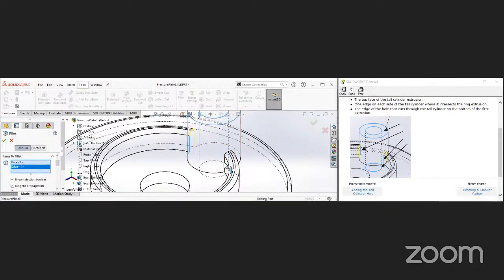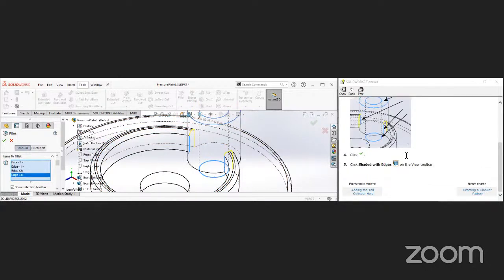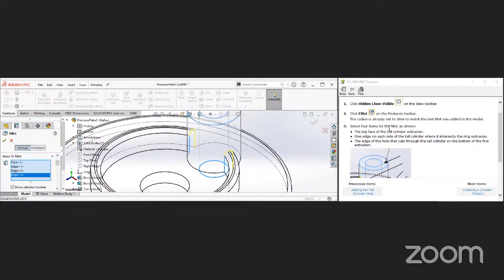Very useful. I click that one and boom, yellow turned all the way around, and it also wants its hidden line at the bottom. And it told us our depth somewhere. It's already set to 2. So SolidWorks usually remembers your last depth, and so it was 2. So we hit OK now.